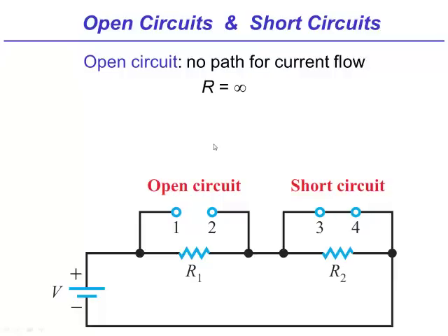When we start doing resistance more formally, you'll see that this essentially means that the resistance between here is infinite. Right? The resistance to current flow is infinite. So going back to the voltmeter case, does that mean that a voltmeter essentially in an ideal world is like an open circuit? Yeah, exactly. That's because it doesn't draw any current, right? That's exactly right.